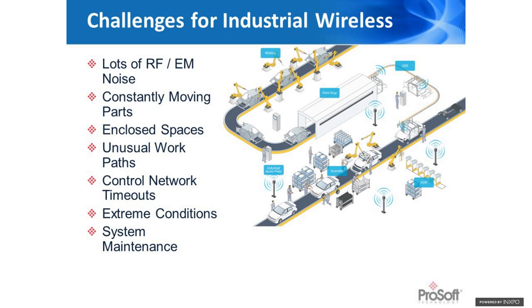If any node loses its connection in a safety network for even a brief period of time, say 50 to 100 milliseconds, it will go to its safe mode. It will assume that it's lost communication, and typically in an automated material handling application, that means the carriage stops, the line stops, and that's not good. That doesn't help gain those efficiencies that these manufacturers are looking for in their applications.